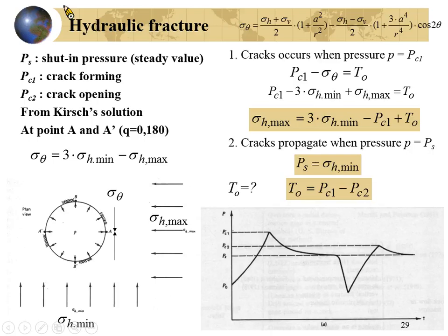Please remember one thing different from this result. Do you still remember borehole breakout? If you have a borehole breakout like this, where is the maximum principal horizontal stress direction? This will be the borehole breakout. The borehole breakout will occur because of the high deviatoric stress.